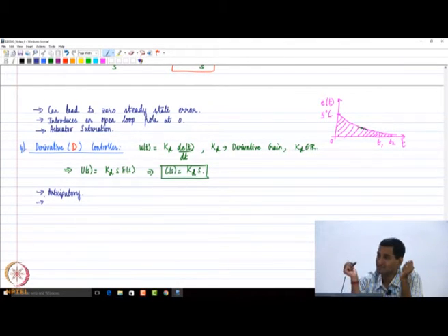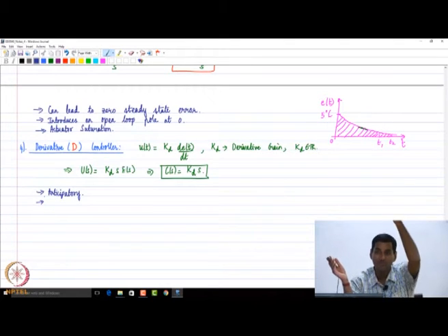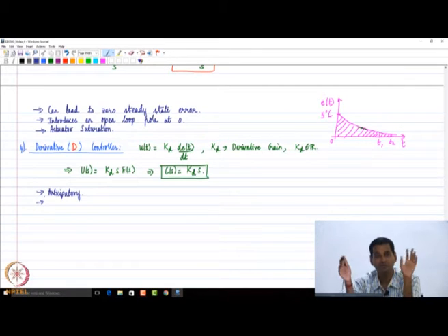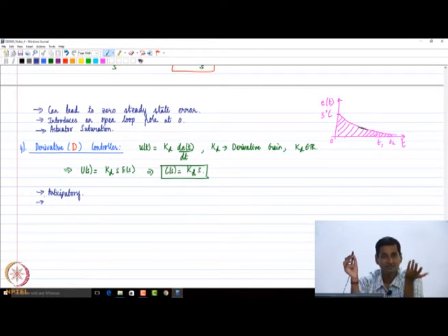For example, let's say I have an air-conditioned room. Suddenly, it's the peak of summer, and I keep the door open for 2 minutes due to whatever reason. What's going to happen? The thermal load is going to increase a lot, the error is going to shoot up, and then the derivative controller will try to use the maximum capacity of the compressor. So the question is whether it's desirable or not. That's a different question to ask, but that's the characteristic of the derivative controller.